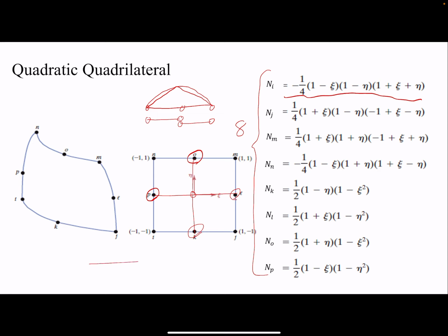But generally, if you have a model that you can only model with one element through the thickness, then it's better to have a higher order element here, because that's all we have. We have only one element. And so let's have that element as a quadratic element or cubic element if we can. So we can have some variation through the thickness as well. So our model could capture whether displacement variation or stress variation or whatever our desired output is.